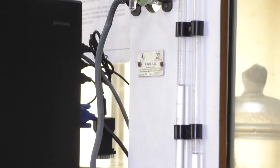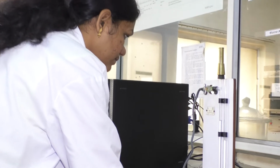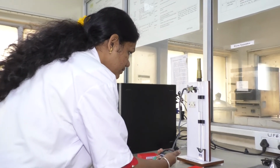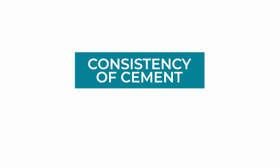Using stopwatch, measure the time taken for the oil to come down from level 2 to level 3. The specific surface area is then calculated with the formula S = K√T. Consistency of cement. This test is performed as per IS 4031 Part 4.